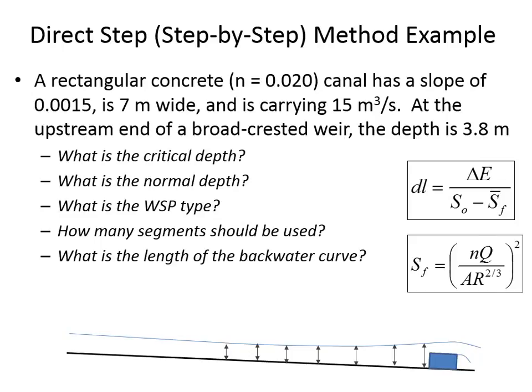Yeah. So remember that the two lines, the critical depth and the normal depth, divide the channel into zones. And so in our calculations, we said that we have this critical depth, Yc, was 0.77 meters. The normal depth is 1.195 meters. And so that makes this zone 1, that zone 2, and this zone 3. The fact that the normal depth is bigger than the critical depth makes it M, because anytime normal is bigger than Yc, it's M. If normal depth is less than Yc, that makes it S. And if normal depth and critical depth are equal, then that's a critical slope, a C. Okay, so it's M because Yn is greater than Yc.